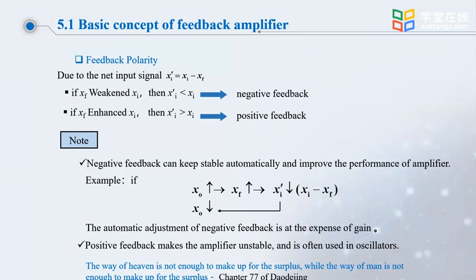Of course, as you saw earlier, there is a cost to this automatic balance of negative feedback: the gain with feedback equals the open loop gain divided by the feedback depth, so it costs some gain. However, gain is easy to achieve in electronic circuits; changing the amplifier's magnification is easy, but it is not easy to keep the whole system stable.